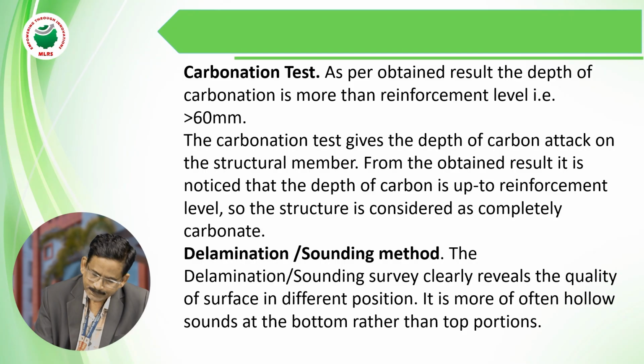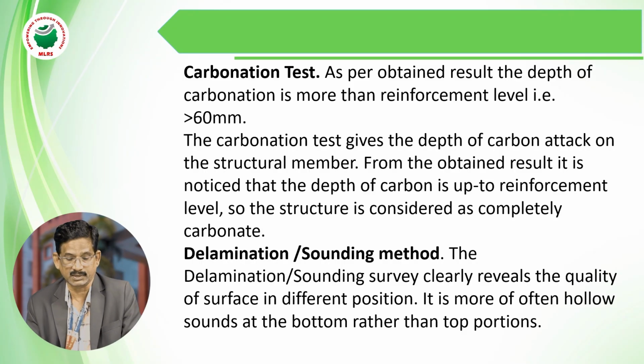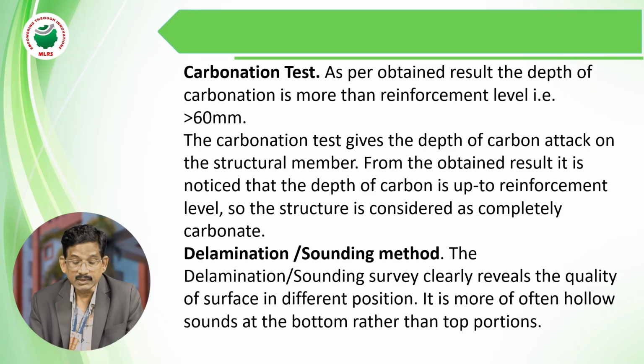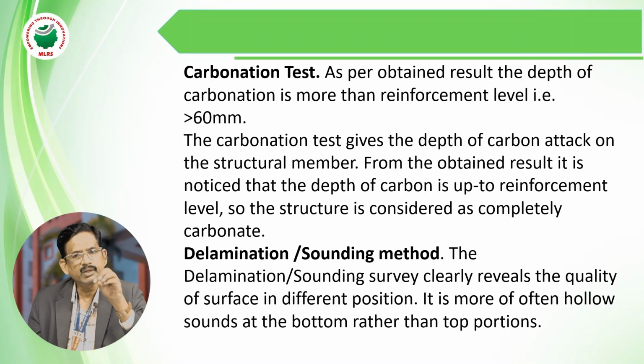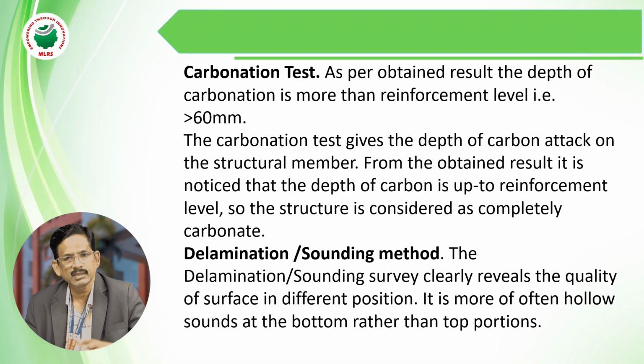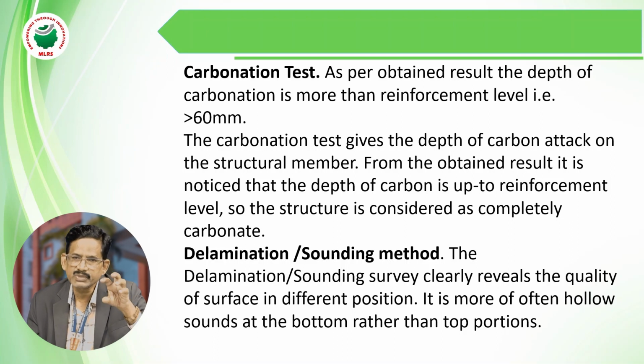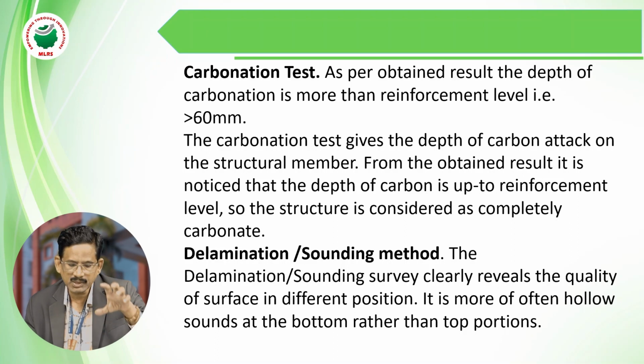After that, go for the carbonation test. As per the obtained result, the depth of carbonation is more than the reinforcement level, greater than 60 mm. So the carbonation test gives the depth of the carbon attack on the structural member. Why did we do the carbonation test in the laboratory? To find how much depth of carbon has entered a particular member, we have to do the carbonation test.